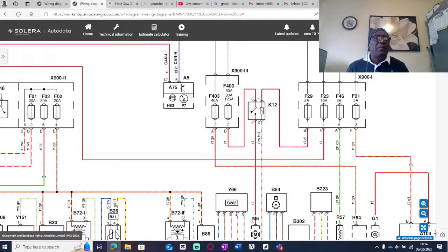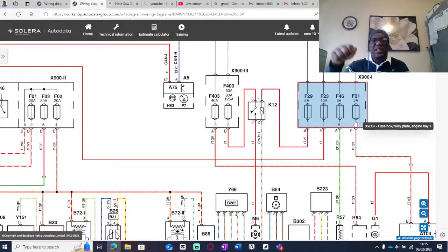So I'm saying to you, if you go on one side of a fuse, then you come to the other side, you should have one sound. I've seen people sometimes go on continuity and then check. Yeah, that's okay as long as that fuse is not powered. That's why I say I like to use a power probe, but not everyone can have a power probe.